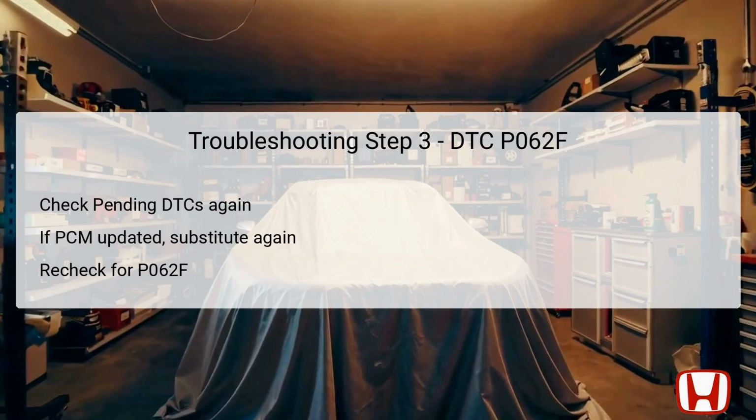If DTC P062F remains and the PCM has already been updated, resubstituting a known good PCM is essential. This double-checking process ensures that the original PCM is indeed failing if the same DTC persists. Should the already substituted PCM not replicate the error, the replacement may confirm that the original module was malfunctioning, warranting a permanent solution. It's an integral part of the troubleshooting to confirm the effectiveness of repairs through diligent rechecking of DTCs.